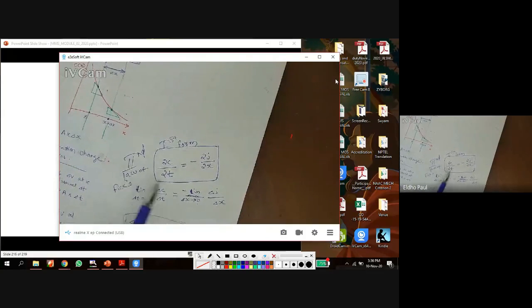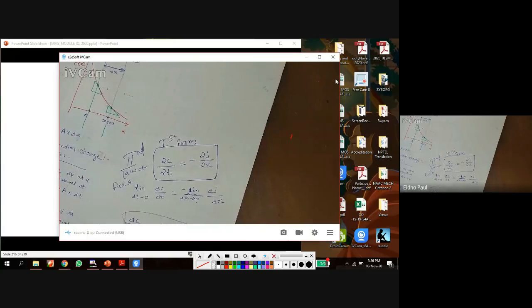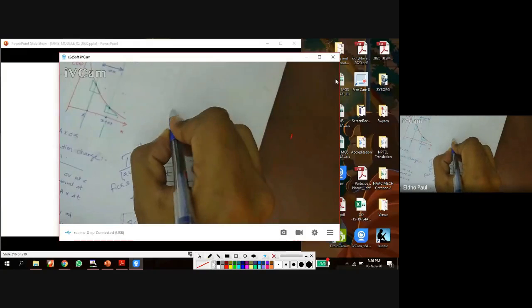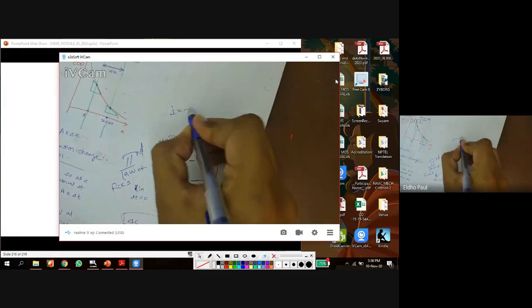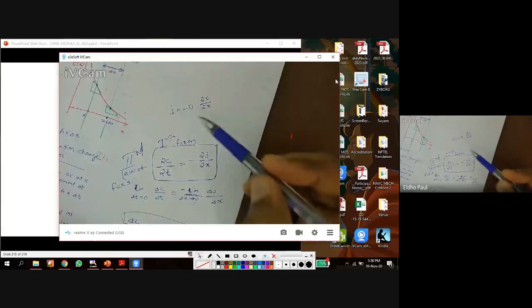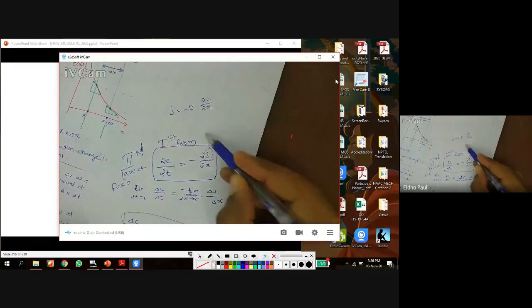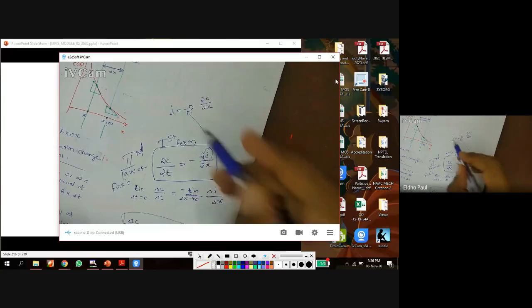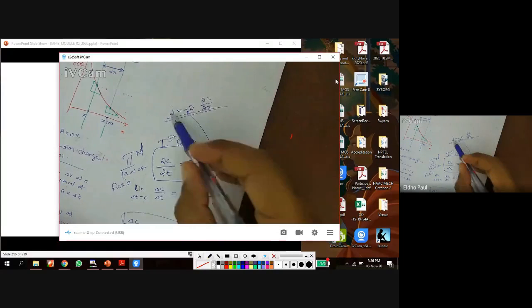So this is the first form of Fick's law, and the second form can be developed by applying Fick's first law on this second law. Next I am going to develop the second form of the second law of Fick. For that, I am going to apply the first law. What is the first law of Fick? J equal to minus D into dou c by dou x. Here I am replacing this j value with the first law.